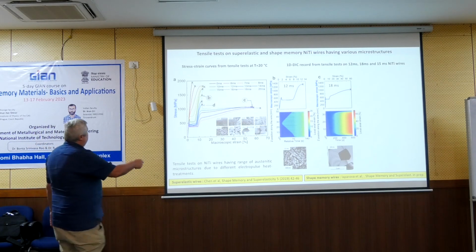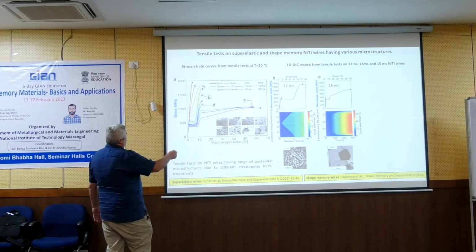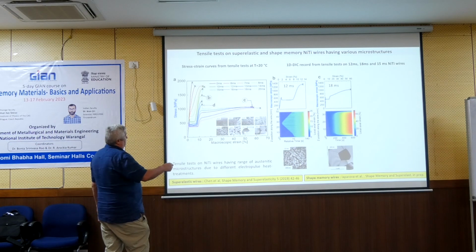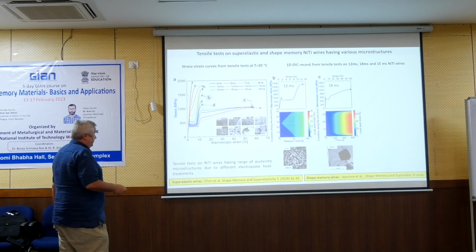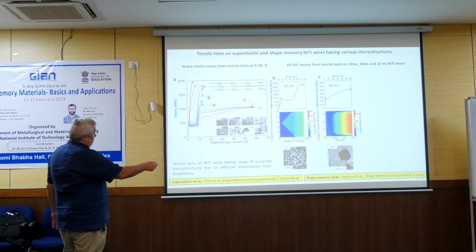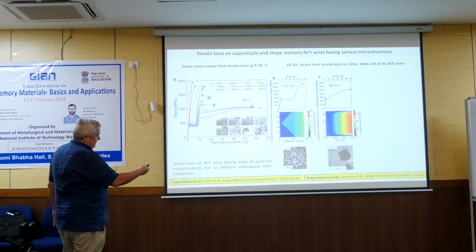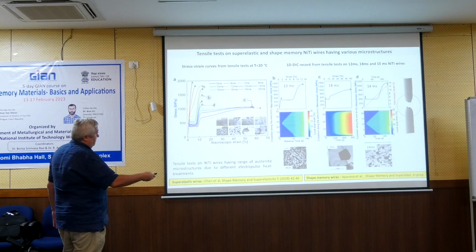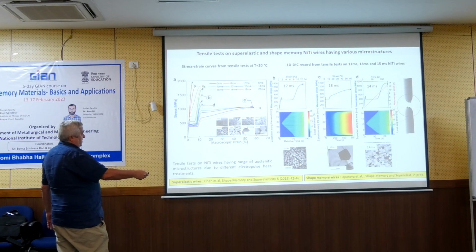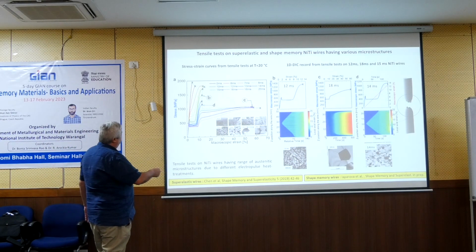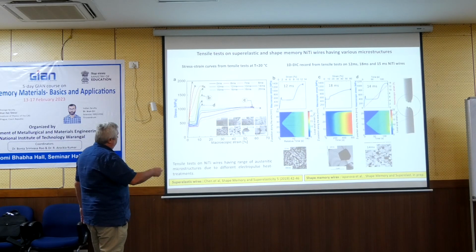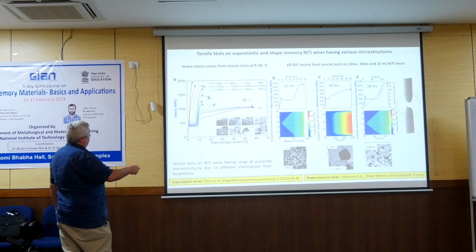So we had to use the wire which will survive this critical condition, which is something like 15 or 16. So we use 15. The 12 wire will stop here, here is 18, we use 15. With the 15 wire we can go up to 50%, but we were mainly interested in the martensitic microstructures here,